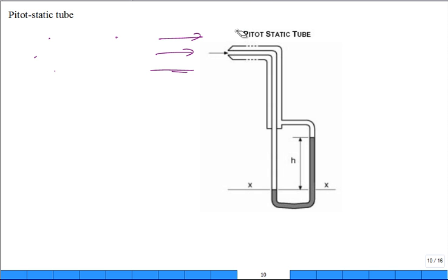Okay. At the very tip, you'll notice a little hole. The flow is not going to go into that hole, because the air that's in the hole goes all the way down here and is connected to a manometer, and it's not going anywhere. It's stationary. So when the flow gets to this, it's got to come to a rest and then move around. It comes to rest and then slowly goes around, but it goes to such a small velocity right there, it's zero velocity.